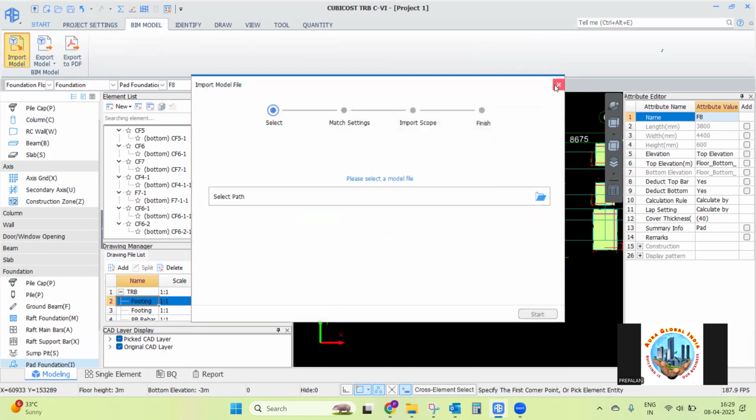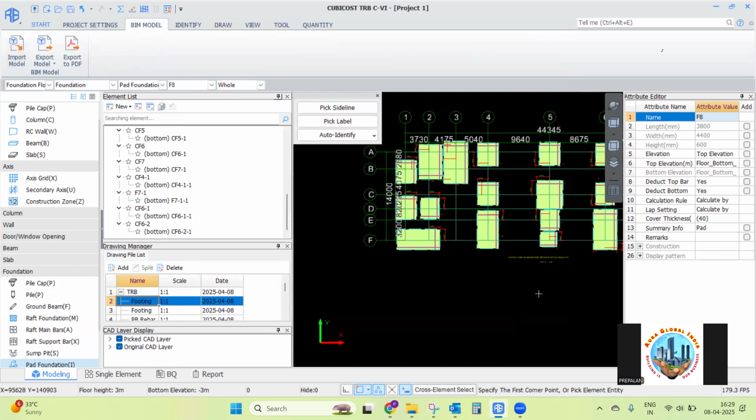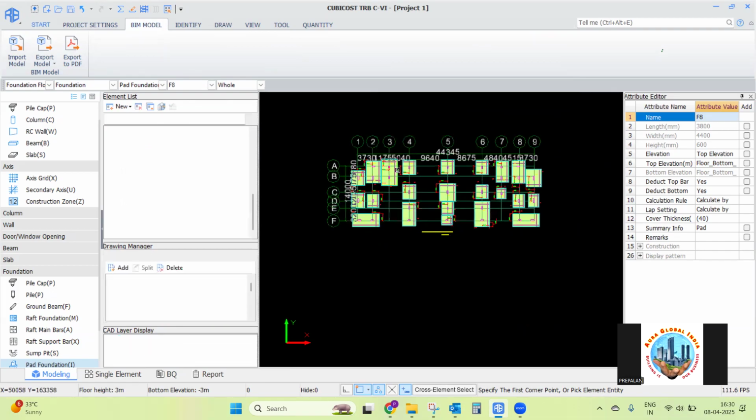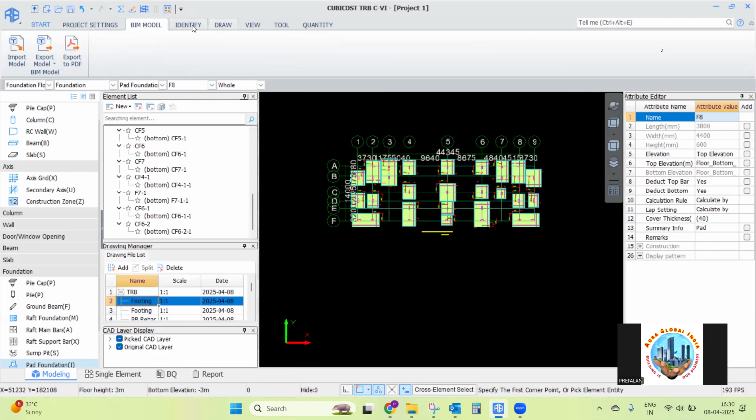Just the rebar information alone, if you have in the form of schedule, you can read it in the form of schedule. The only thing is, whatever label they mentioned in the schedule and your TAS model should be the same. For example, if the footing label name is F1 in TAS, here also in the schedule, F1 should be there. So that the rebars will be input into the model. You don't need to make the model again. That is easy for us.